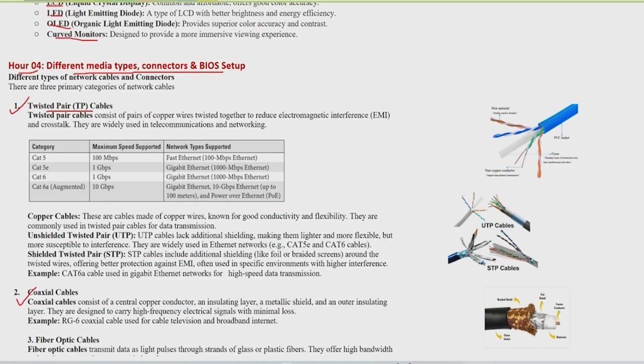You will be thinking, I have bought a very good cable, I don't know why the data is not going properly on my network. But when you go to the layout, you will see that your network cable is running with the same electrical cable. So that is the problem. You have to separate the electrical cable from the data cable. Whenever you are planning to run your network cable, avoid the electrical cable nearby. The electrical cable should go one way and the network cable the other way.